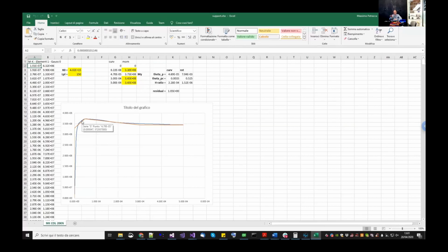So of course, one assumption is that when you use the lump plasticity with a phenomenological constitutive model for moment rotation, you cannot expect an interaction with the axial force. So in this case, we are directly computing the moment rotation for this specific value of axial force, okay? So in a while, I will show you the parameters that you need for the modified Medina-Krawinkler, but basically here, I already computed some of them.